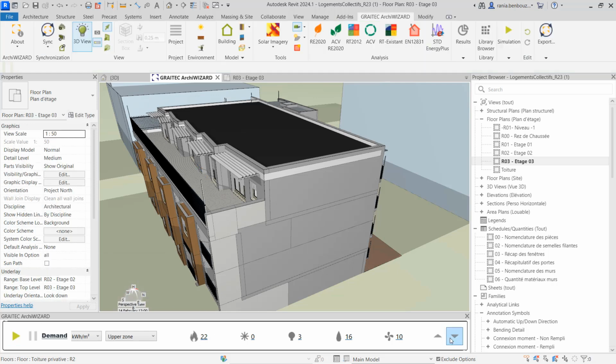So I found an optimum with medium length shading blades, and we are going to conclude in real time the results of this iteration. So if I chose this length of solar shading, I have successfully reduced 247 hours of thermal discomfort. We were about 800 hours, and now we are at 641 without any more raising the heating demand.